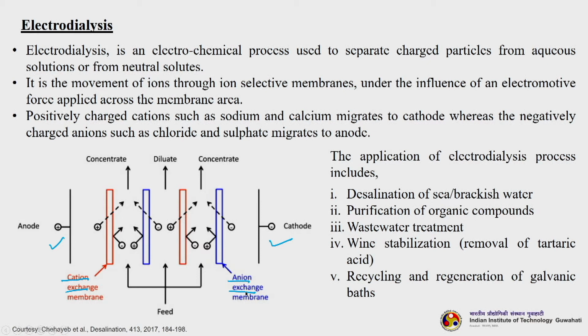As we understood previously in this lecture, the cation exchange membrane will have fixed anions and anion exchange membranes will have fixed cations. So, feed is passed from below, I can pass the feed from the top also, then I get dilute from here and concentrate from here.